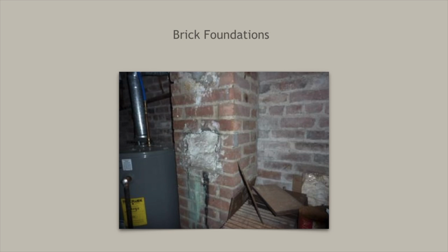the brick's structural integrity. As a result of the bricks absorbing moisture, the water would wick up to the wood joists. As a home inspector, is this an area of concern? Yes. Be sure to look at each joist and use a screwdriver to gently check for wood rot. In some cases, rotting joists will collapse where the wood joist sits on the top of the brick foundation.